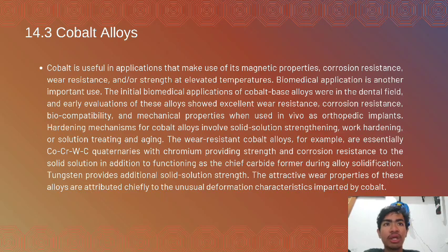The initial biomedical applications of cobalt-based alloys were in the dental field, and early evaluation of these alloys showed excellent wear resistance, corrosion resistance, biocompatibility, and mechanical properties when used as orthopedic implants. Hardening mechanisms for cobalt alloys involve solid solution strengthening, work hardening, and solution treating and aging.